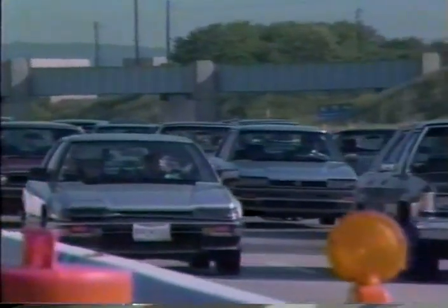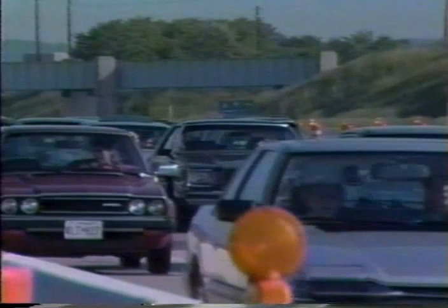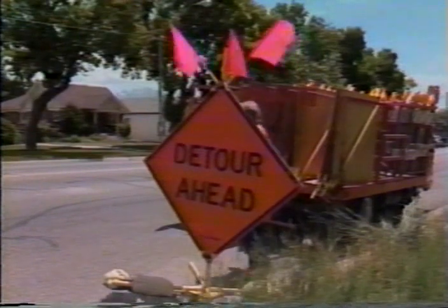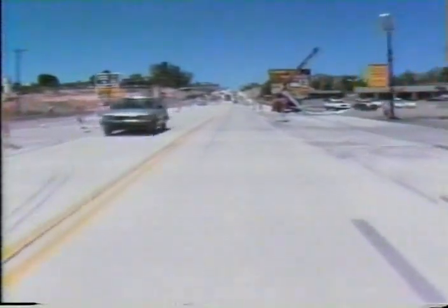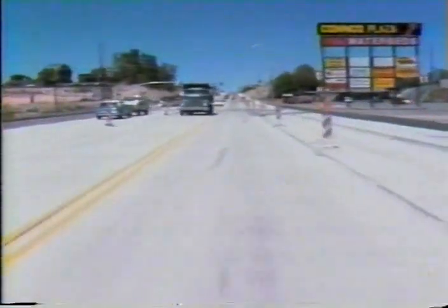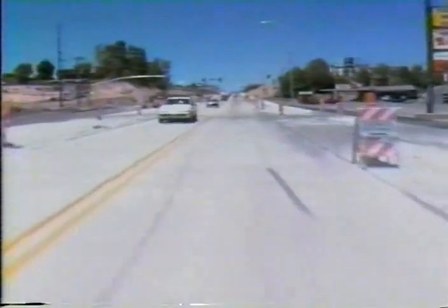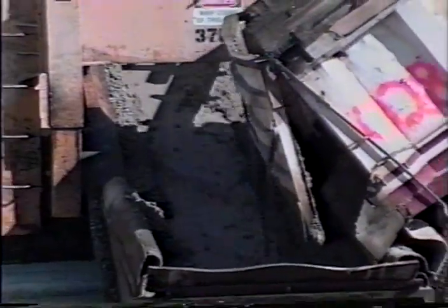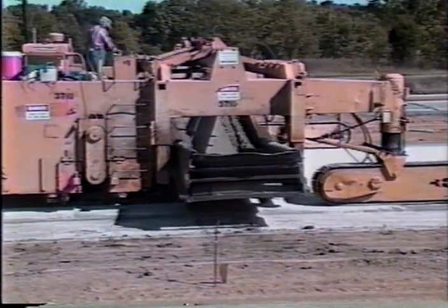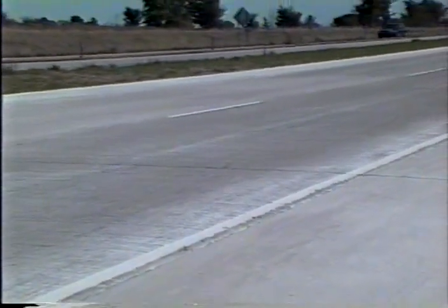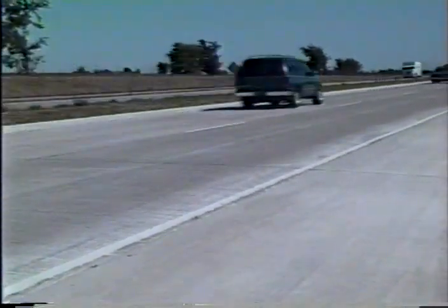In the past, constructing concrete overlays disrupted the normal traffic flow. Roads had to be closed. Detours had to be set up. Well, you probably remember. But recent developments in concrete technology, such as fast-track mixes and zero-clearance pavers, make it possible to construct concrete overlays with much less disruption to traffic than before. Now a concrete overlay can be placed on one lane while maintaining traffic on adjacent traffic lanes. And the pavement can be open to traffic in 12 to 24 hours.